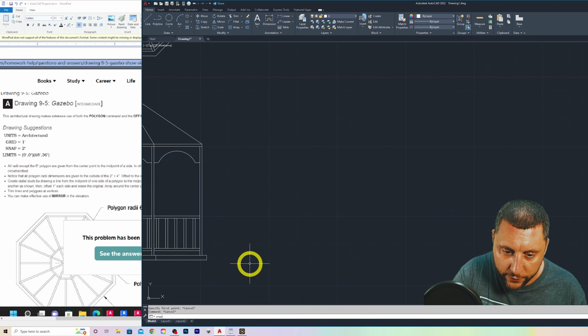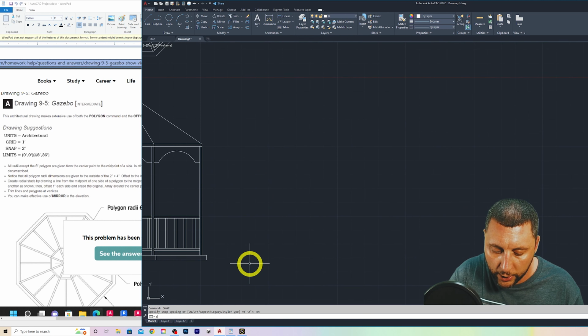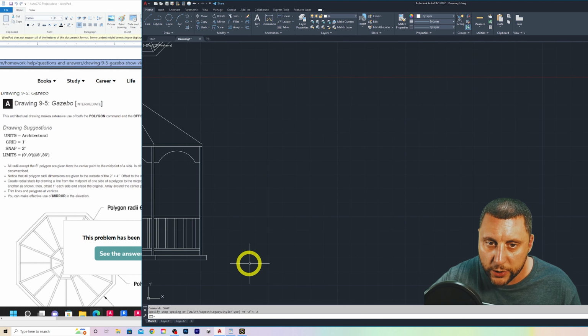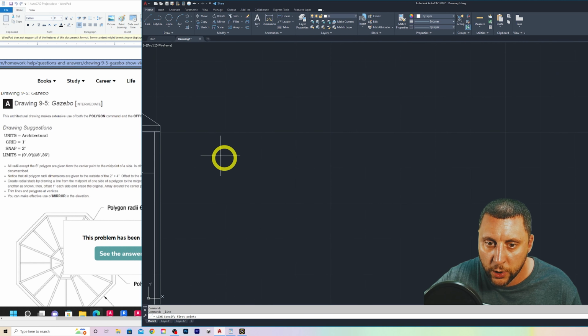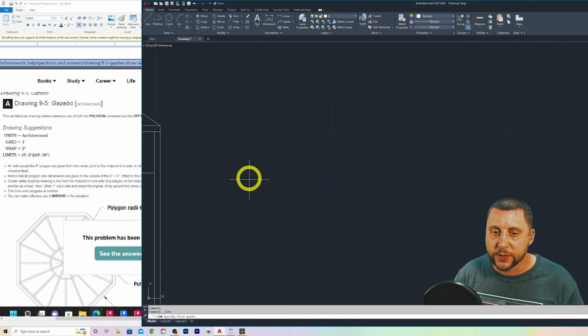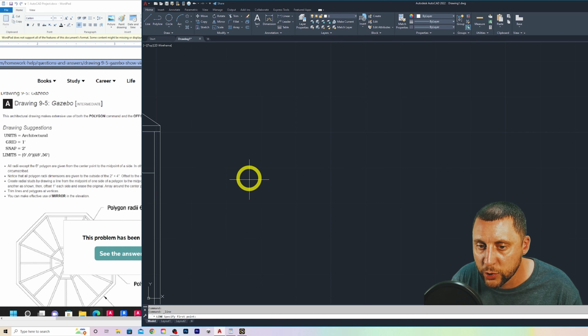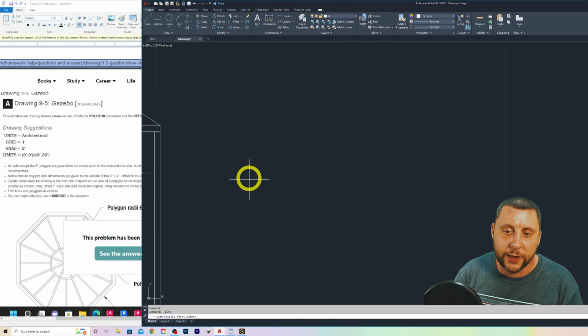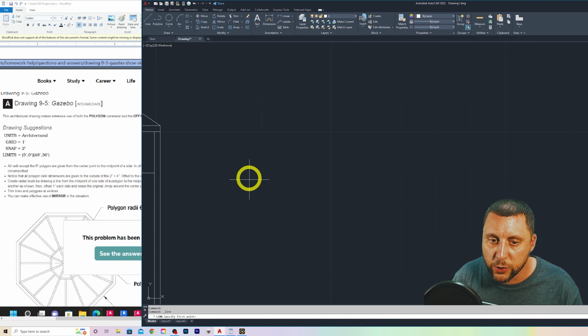All right, so snap. If you turn snap on and you go back into snap and you do 2 inches and you're in a create tool, it's going to snap around every 2 inches. The point of this is that the drawing lines up on this invisible 2-inch grid, meaning there won't be any lines set at 1 inch or anything like that. Because you've got 2x4s that you're using to build this gazebo, okay?